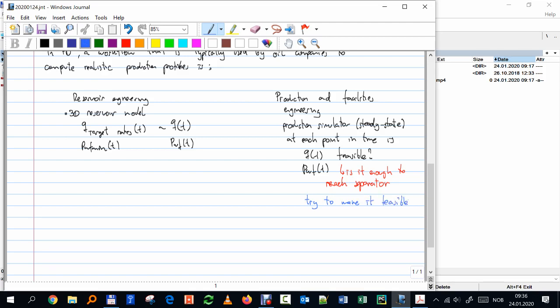Okay, either by changing tubing size, by including artificial lift, or maybe by doing some gas lift, they try to make that rate work, okay? Because supposedly the reservoir engineers are applying those rates because they lead to higher recovery factors. They have some objective for using those rates. They lead to high recovery factor, high revenue. They think that these are the best rates.